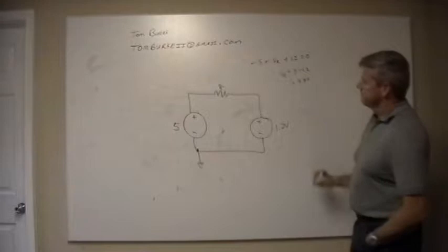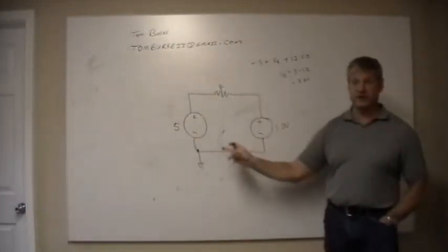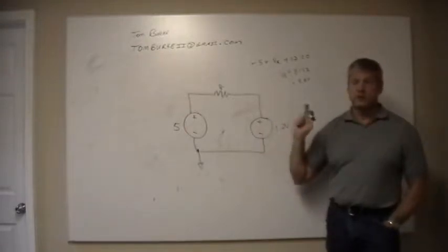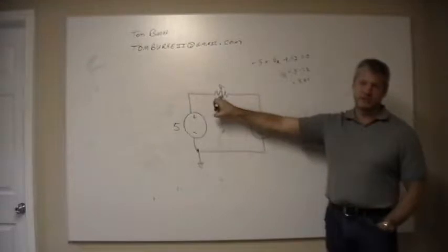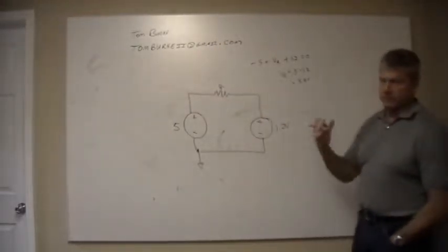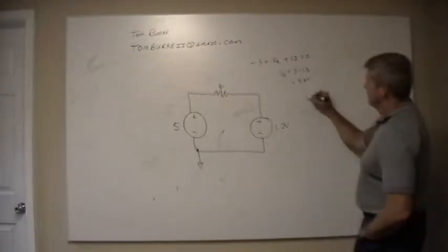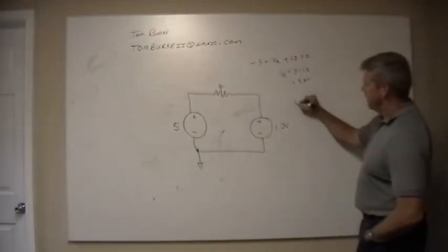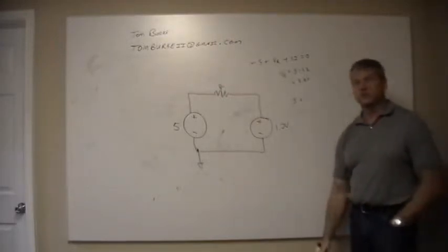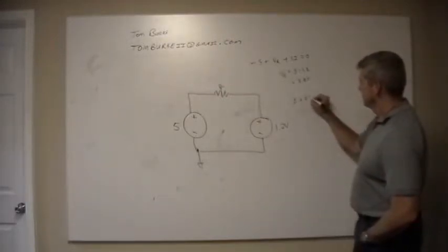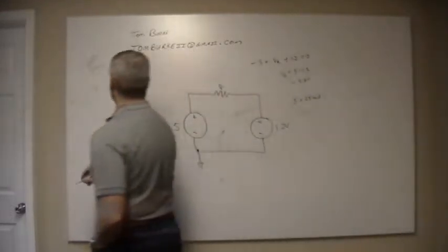3.8 volts. Now, when you do this, remember I talked about you can have infinite current. You want to limit the current. In this case, when you're doing this, R is called a ballast resistor. I don't know where the name ballast comes from, honestly. I wish I could give you that piece of information, but let's say that we want I to be 25 milliamps. Oh, do I need to go through this again, don't I? Because we got some new people.